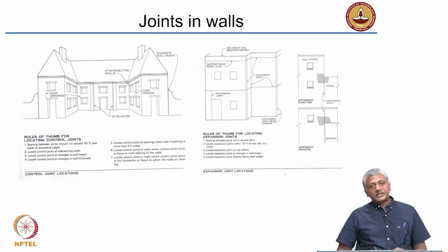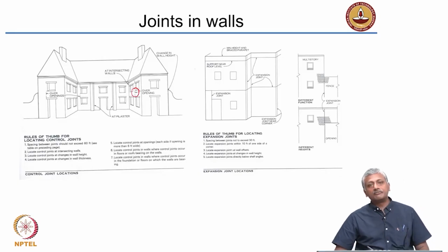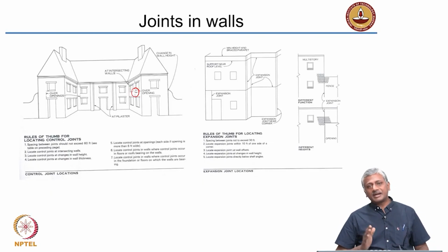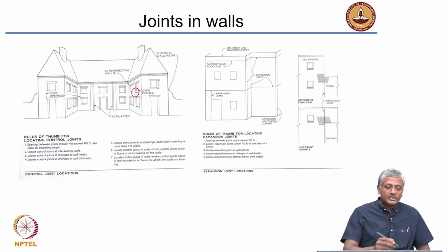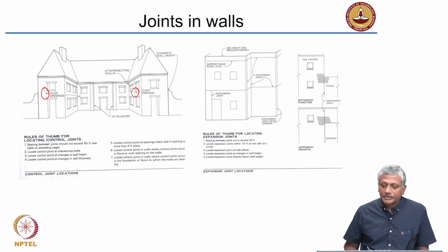Now, again, the expansion joints are not only provided for running length, you may also want to provide it wherever you are seeing openings, wherever you are seeing window openings, because one of the common features you will observe when you see your own house, for instance, you will see that many of the cracks are emanating at corners and wherever the openings are there. So, to avoid such cracking and avoid failures, generally your joints may need to be provided over such regions. All you are simply doing is providing some free movement of the different structural components in your construction. Okay. So, those are some examples.